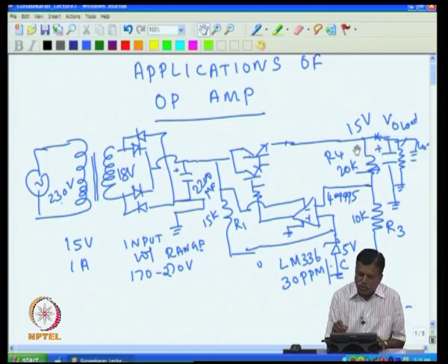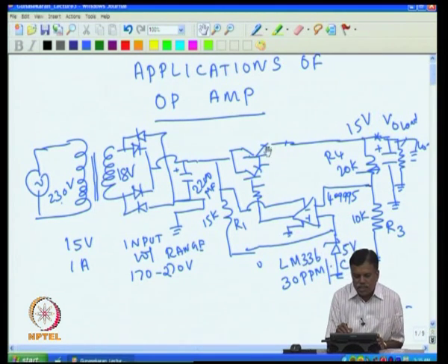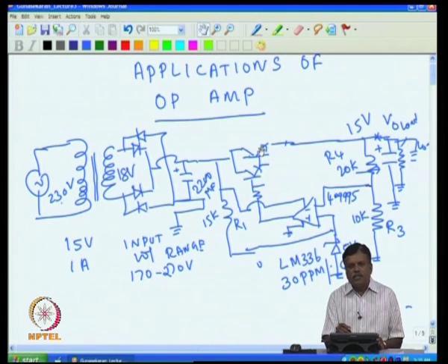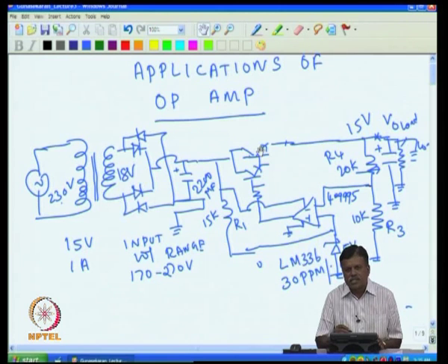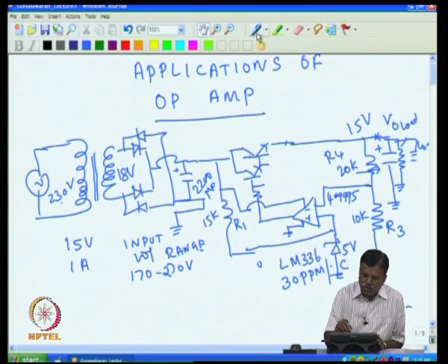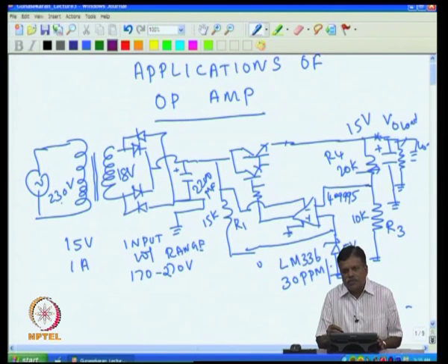So, depending upon the load, the transistor heats up, but whatever may be the case, I have to make sure that the transistor will not go bad, or that the life of the transistor is not getting reduced because of the heating. Now, I introduced the term life of the transistor because if the heating is more, then the life of the transistor is less. This is because, assume that you are using it for a TV. In the TV, what happens is you will be switching on the TV and watching the program in the morning, then after some time you will switch it off.